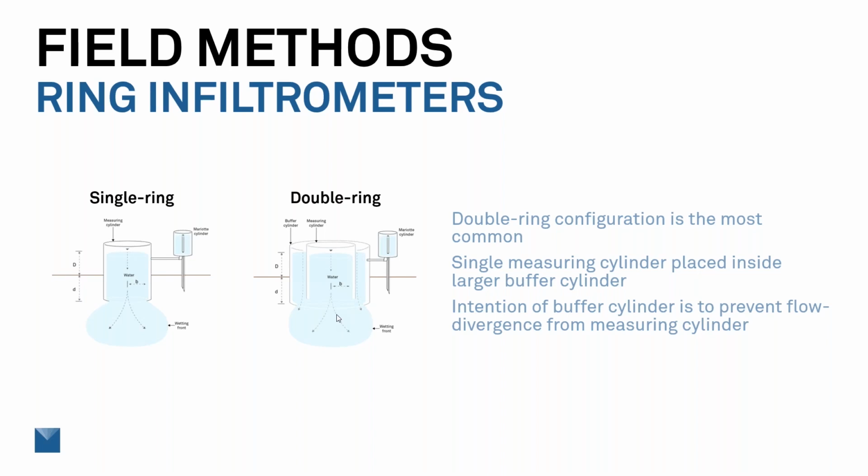So with both approaches, we have to make corrections for three-dimensional flow, and those corrections involve estimating the soil properties, or the alpha value, this macroscopic capillary length factor that we use to estimate the sorptivity. We run the risk of making errors there because we're typically making assumptions about the soil type and structure, so we can sometimes use a wrong value to correct for three-dimensional flow.